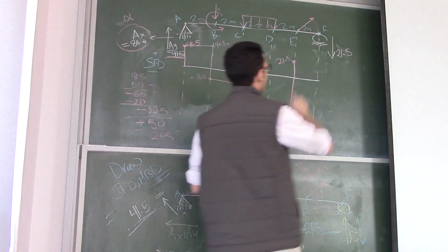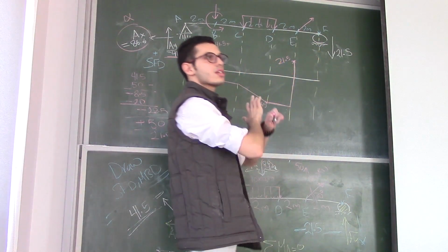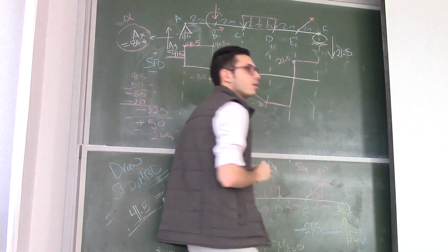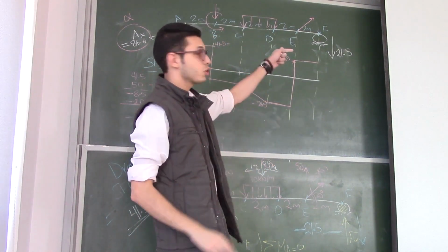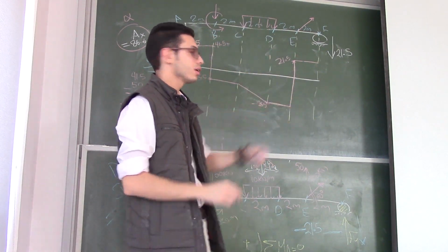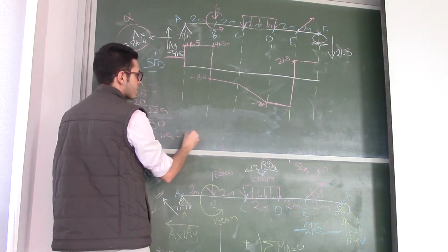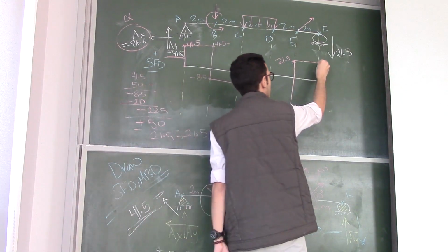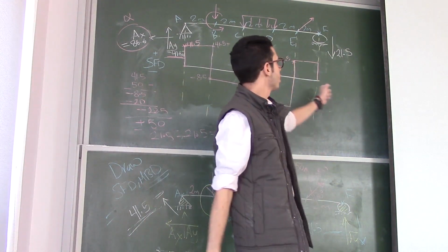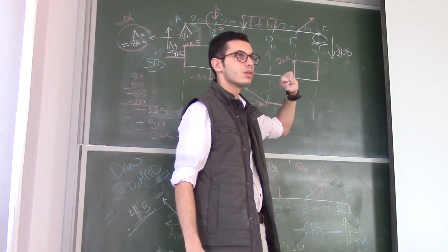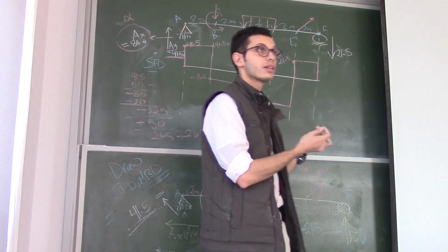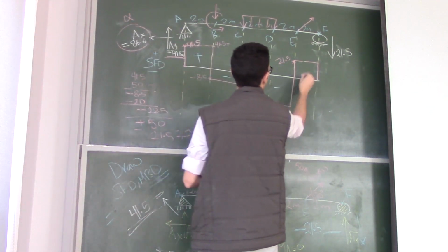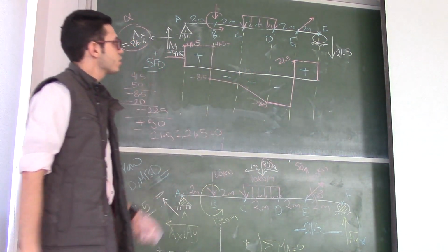Now, between point E and point F, there is nothing acting, so I will remain constant, like this. Finally, at point F, I have a 21.5 downward, right? So this 21.5 minus 21.5 will equal 0, and it's closed. The final value is 0. That means my drawing is correct, right? Yes. So, positive, negative, negative, negative, positive. This is the shear diagram.